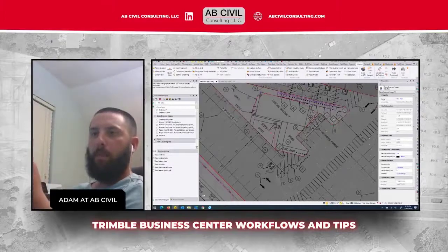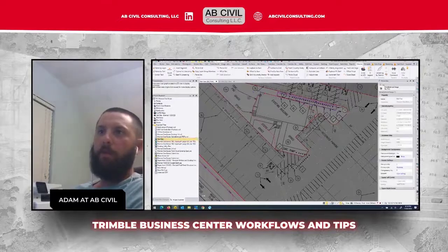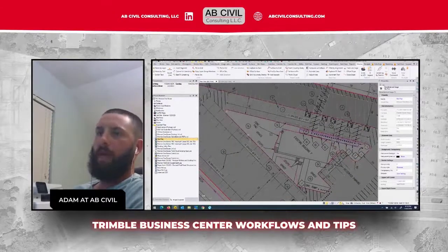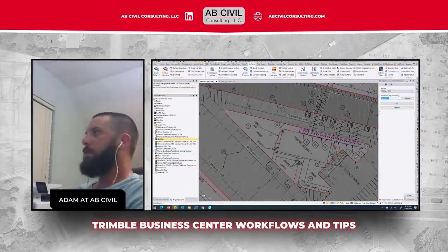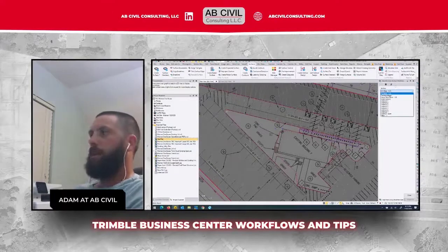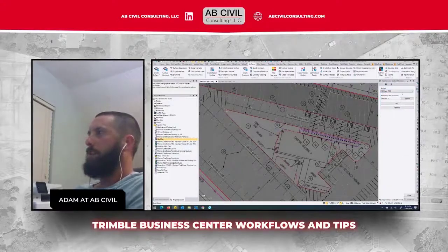The way around it is down at Project Explorer. Click on Project Explorer and collapse surfaces. Then I'm going to expand imported files, and it's already on site plan right here. So when I click on it here, now it's selected. So I've got one item selected. I can't select it in Business Center in the view, but I can select it in the Project Explorer menu. So it's as simple as just going to Surfaces, Surface Members, add or remove surface members. I want to add this PDF to my finished design offset minus 1.33. Just going to hit add.